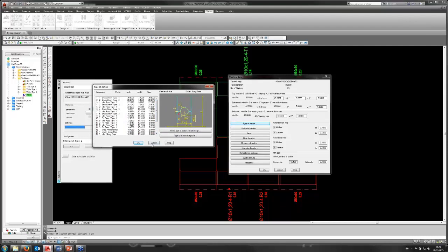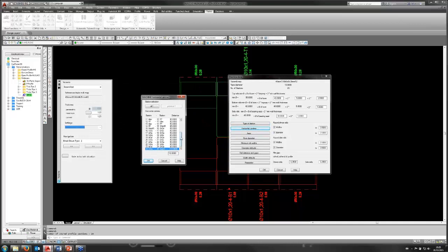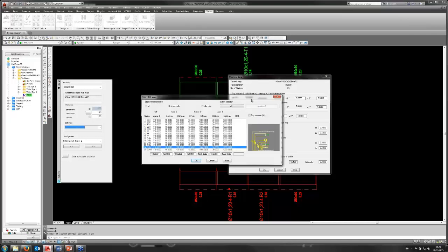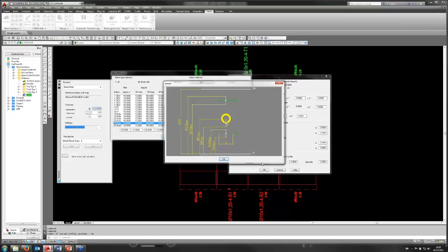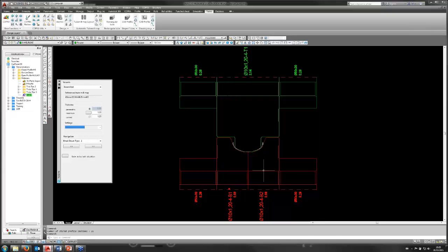This is our tube mill map. Our horizontal centres, of course, and this is derived from our roll form machine. So this is the distance between the physical passes themselves. Our axes data, you can see here in the schematic what we would define. Root diameter for our profile, minimum roll widths, diameter defaults, and so on. So these are all parameters we select for our specific design.